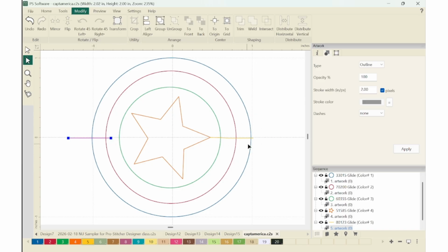The other thing is, the reason you're still seeing this yellow line on the right side is that it's going to show this ghost purple until I finish everything I'm doing. If I click off of it, then all those changes are going to be made. If it really bothers you in the middle of things, you can right click and hit update path and it'll change all of that.